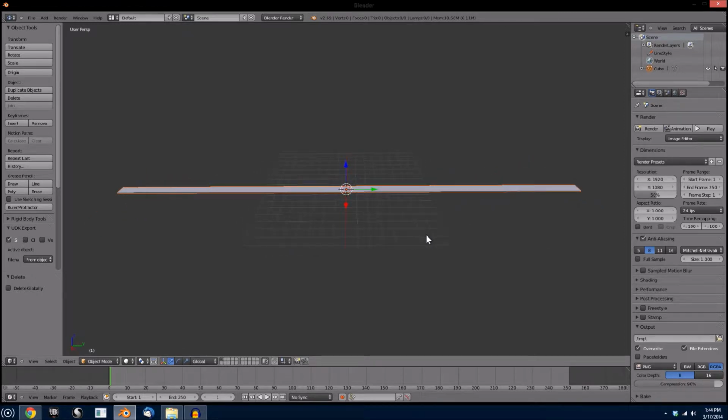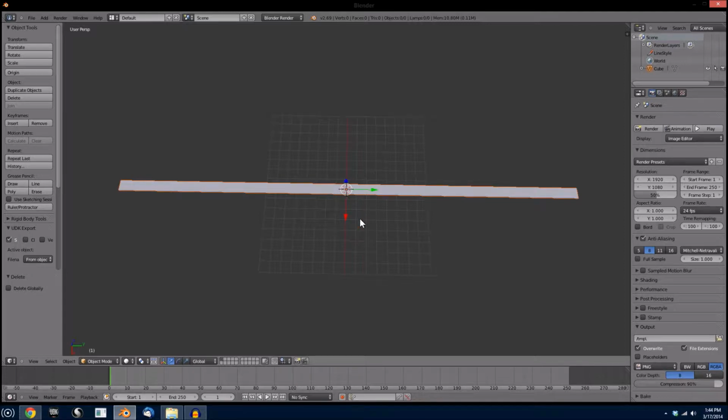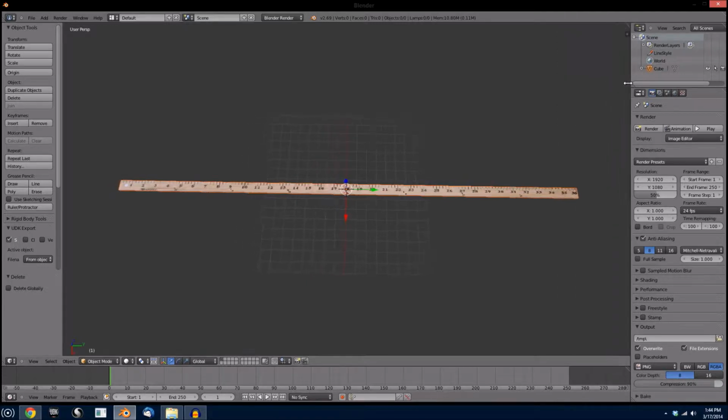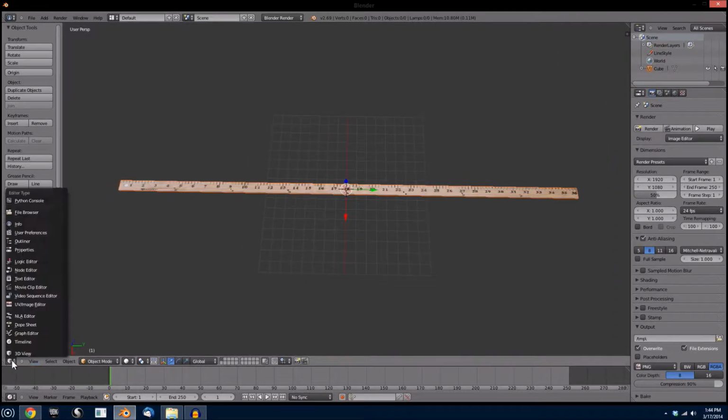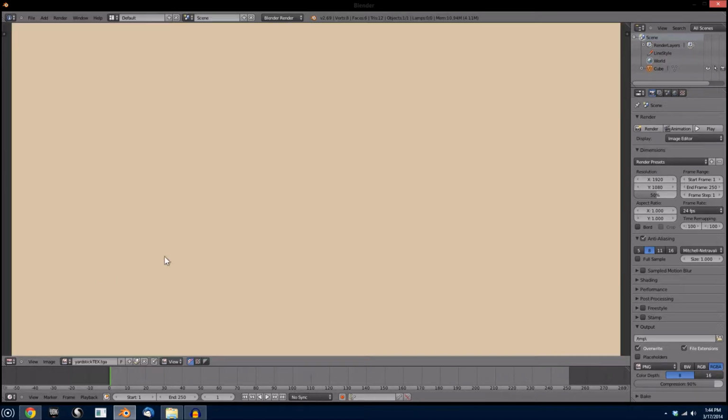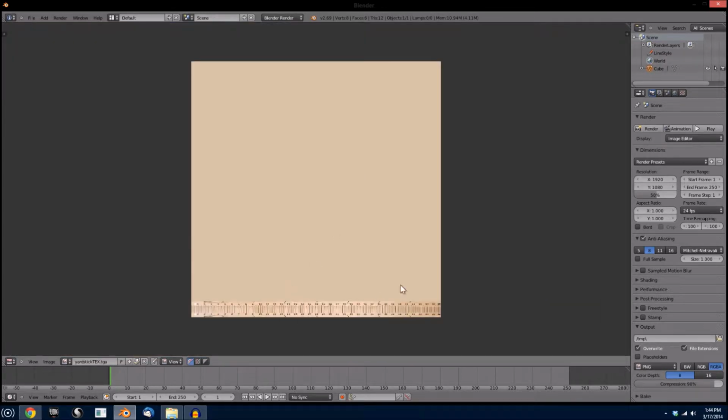Now this is not going to show anything on the yardstick. You're not going to see any rulings there. However, it is textured, so if we go into this panel here to the right, go to shading and select textured solid, then we actually see the texture that is applied. If you go into UV image editor, it will be the yardstick texture.tga, and this is not by any means an optimized texture. It is just used for scaling purposes.